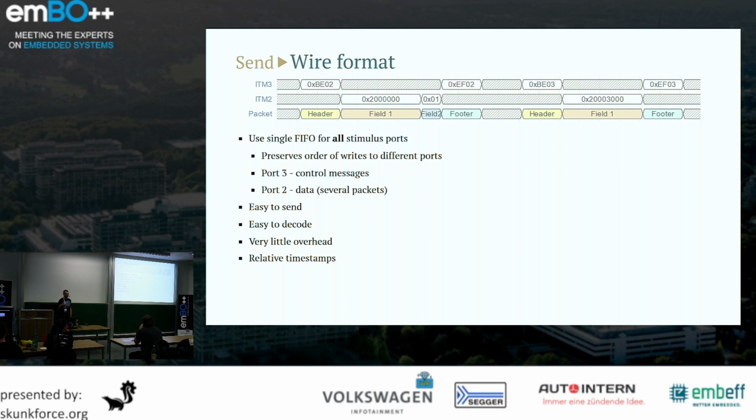send more than 4 bytes of data per trace event because, for example, for a queue, you would like to send the address of the queue, which is already 4 bytes. Then add some additional flags like was it an ISR, was it a successful operation, what is the updated number of items in the queue. And by defining this explicit packet format, we can easily recover entire packets of data, even if it was truncated in the middle, because we have explicit start and stop.